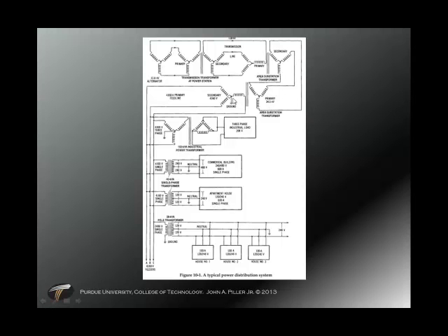We head out of that and we go out to a secondary into a 4160 line. A 4160 line would be distribution in a neighborhood kind of a setup, down a city street, in an industrial park. So here we go to a 3-phase load and an industrial load. Here would be a commercial building and an apartment house, and then split off into other homes.